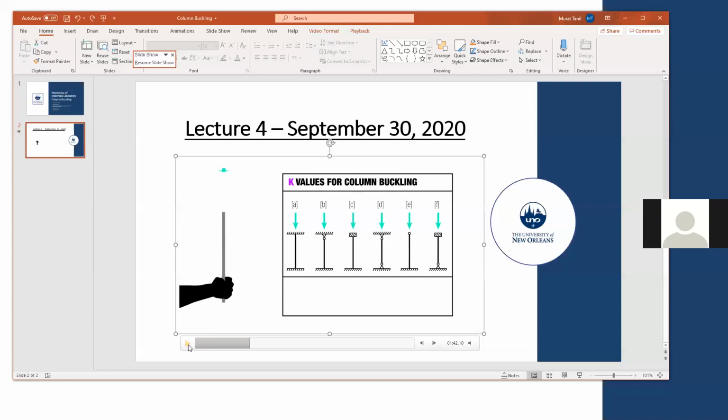It's more flexible and it has less P critical load. And you have E. On E, it is fixed at the bottom and allowed to kind of move around at the top. And the last one is F. It is free to move at the top, but fixed to rotate. At the bottom, it's pin.